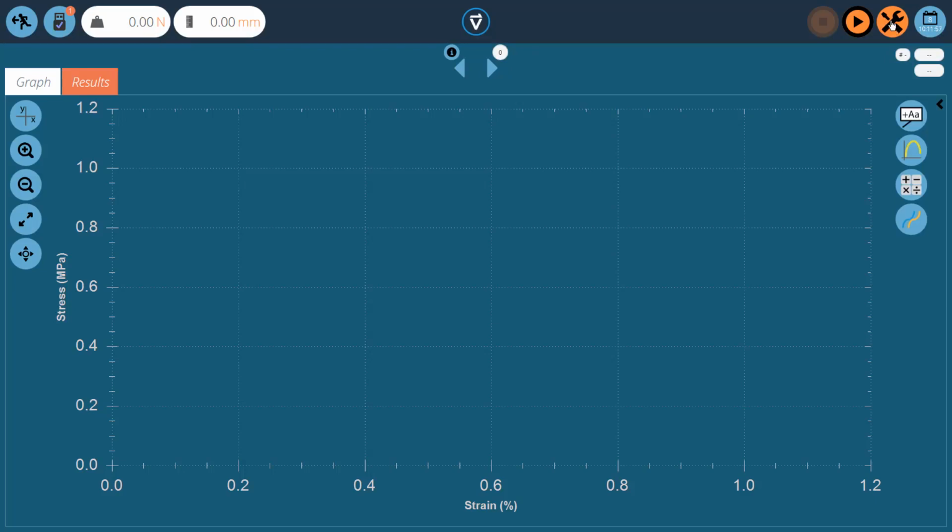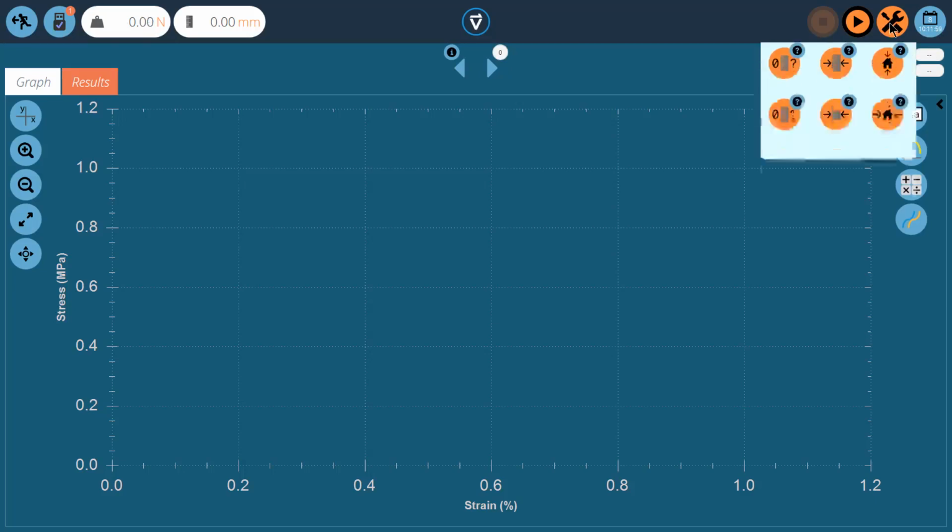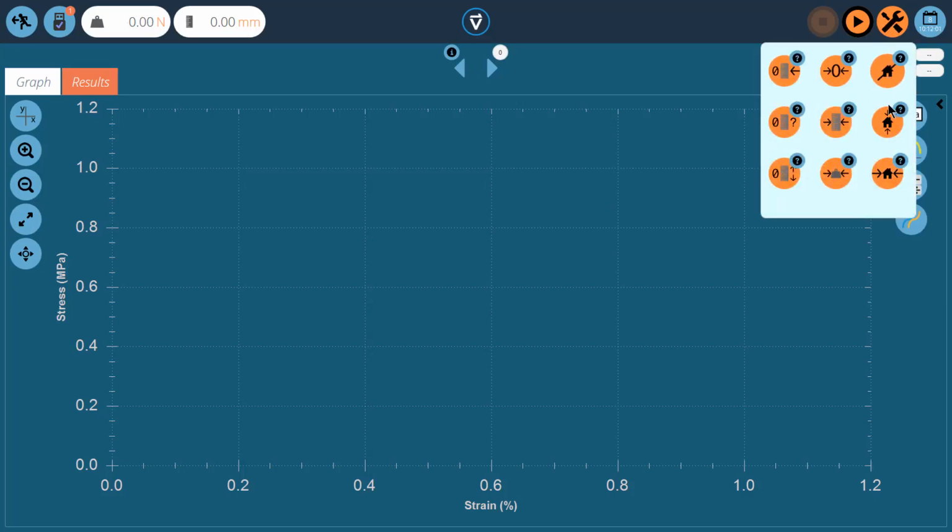In the graph screen, we've got 3 new buttons under the toolbar. We've got a set home position, a clear home position, and a move to home position. Set will obviously set the home position. Move to will move it to that position. If you've set one of these and you want to get rid of it, you can use a clear home position. And during your timeline operation, what it means is it will go back to its first hard 0 rather than a predefined home position. Those are the new home position feature buttons.